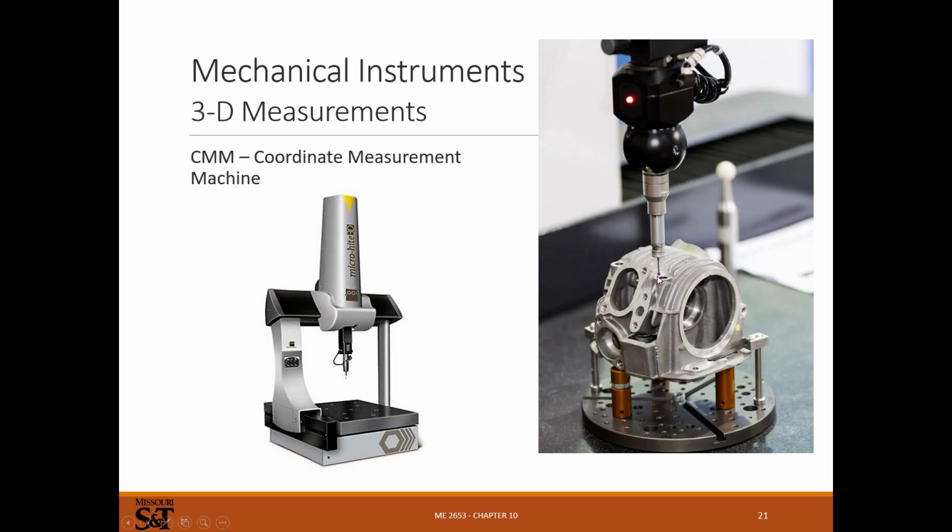And then this probe is usually mostly a sphere here, and so you can contact it pretty well everywhere but on the shaft of this thing. And then this will be on a head that you can rotate. This one would probably be 3 axes, but you can get ones that can rotate around in 5 axes. This one would be one you'd manually move around.